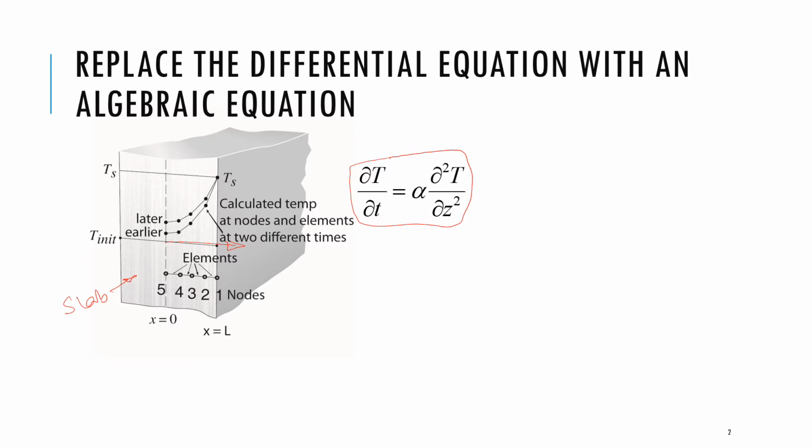And so we also have two boundary conditions. One can be surface temperature given, and the other one is the symmetry. So it's del T del x at x equal to 0 is 0. So we need to only solve for 1/2.